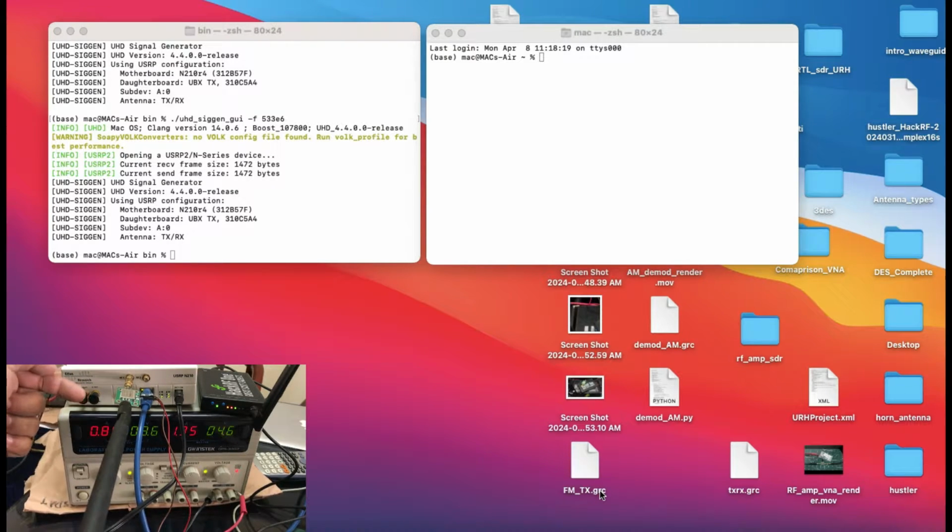Alright, as you can see, my power amplifier is being biased, and this is biased through a power supply. The power supply is not turned on. It's powered by a fixed 5 volts power supply here, so it has nothing to do with the reading that you see over here. On this port you have a fixed 5 volts coming out, and maximum you can draw up to 3 amperes.